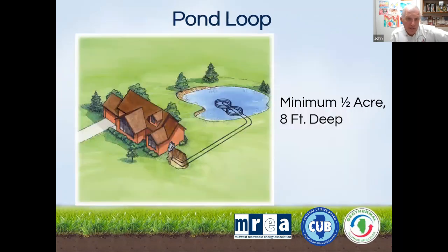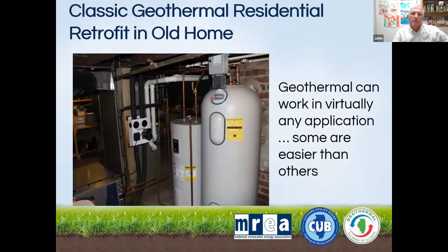And then lastly, as I mentioned, you can put loops in a pond. Now, most of us don't have a pond in our backyard, and usually we don't have a pond that's large enough. But for those people who do have a pond that's big enough and deep enough on a year-round basis, putting the loops in the bottom of the pond can work perfectly fine.